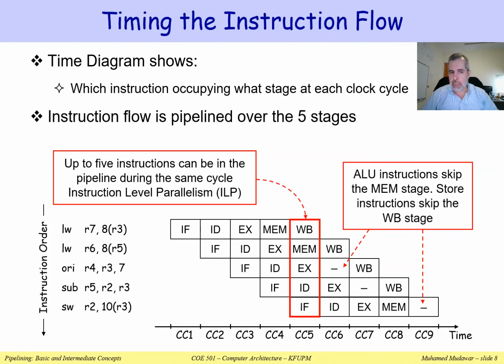So the first load instruction is now in the write back stage. I'm just writing the name of the stage. The second load is in the memory stage. It's reading the data from the data cache. The third instruction, the or immediate instruction, is in the execute stage, so it is being executed on the ALU. The next instruction, the subtract instruction, is still being decoded. It's in the instruction decode stage. And finally, the last instruction here, the store word instruction, is in the instruction fetch stage. It's actually being fetched from the instruction cache.